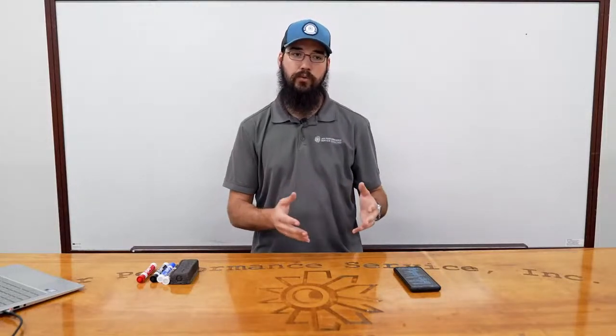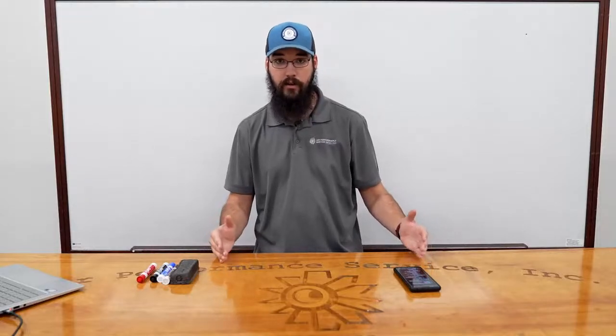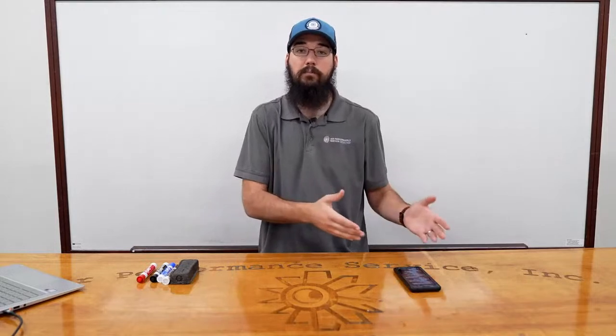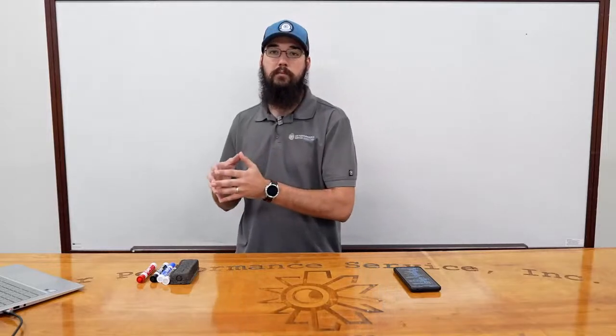RTUs and the regular split systems might have an external static, that means between supply and return, of half an inch if we're doing good, right? Or even as low as 0.2 inches of water column. So that's the difference I'm separating. I'm going to hone in on what we would consider a low static system, and the next class will be more focused around the high static side.